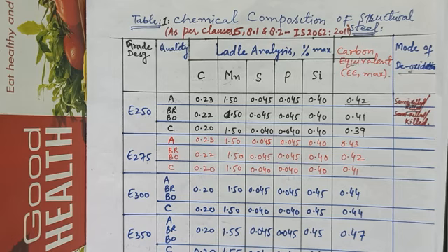Then lime is charged to slag off further impurities. Ferromanganese, ferrosilicon or aluminium are added to deoxidize the liquid steel. Otherwise, the oxygen present in the steel will appear as oxide inclusions in the solid state, which will be very harmful for the structure of steel.